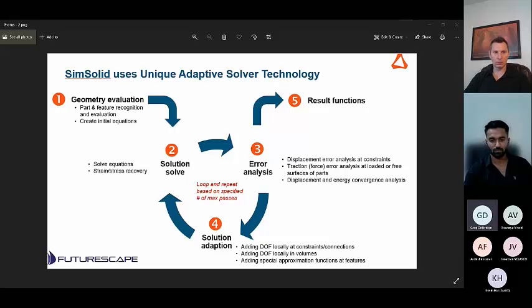So basically, in finite element terms, you've created one giant element that is the exact shape of the part. So it is truly meshless. And once you've created that, it solves it just like finite element analysis, using the same method behind the scenes, but from a very ridiculously 100th order polynomial equation that describes the edge of one part, rather than a simplistic shape function of a linear relationship between two nodes on a hex element or something to that effect.